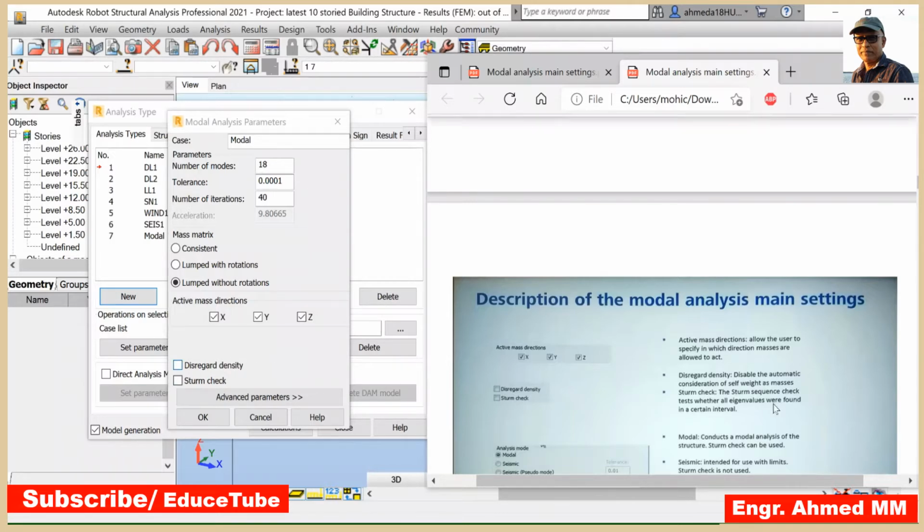Disregard density. Here it says, disable the automatic consideration of self weight. Basically, the software converts self weight to mass. That is why we must leave this disregard density option as it is.